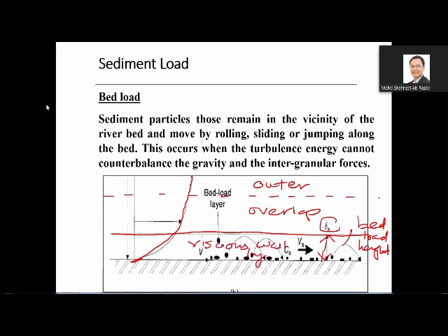Viscous wall layer. And this is where your law of the wall theory is derived, based on these 3 layers. So what I want to say here is that our bed load transport actually moves in this viscous wall layer only. Why? Because the turbulence happens above this viscous layer. Turbulence happens within the overlap layer or up to the outer layer.